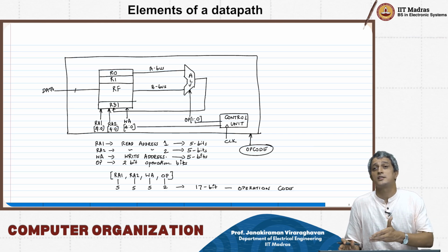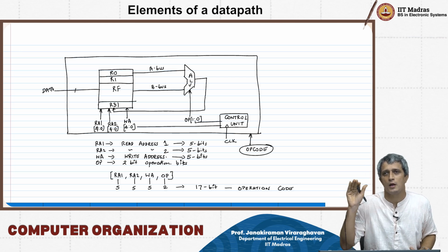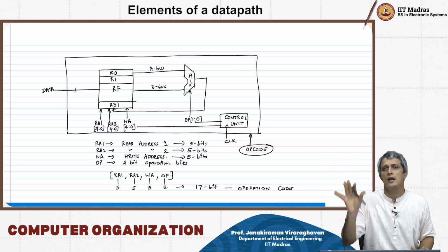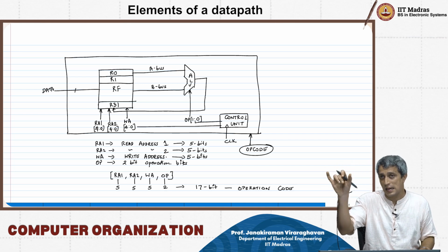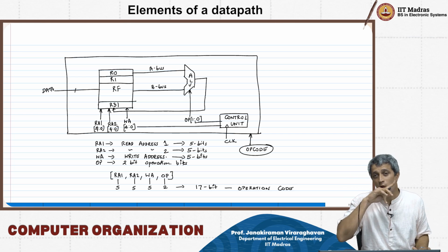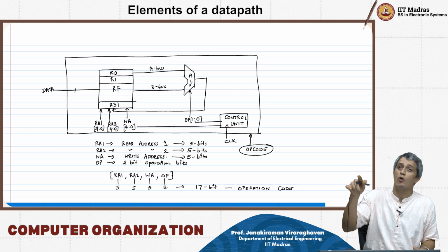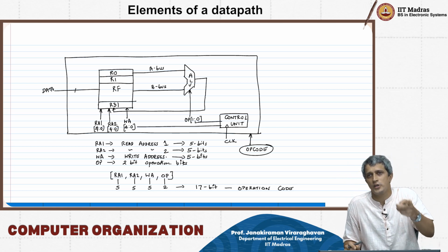Now where does this input get fed from? It gets fed from the code memory, where I store the program in a certain sequence. What gets stored in the memory is a 32-bit number per address that stores the opcode, and that opcode is what we saw as a mnemonic in the earlier part of the course.